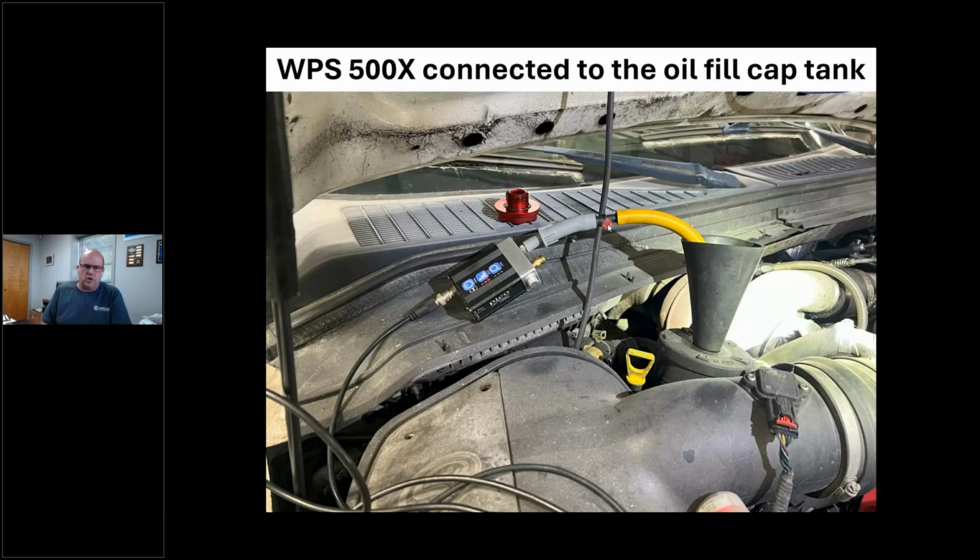If you guys have watched my engine mechanical class with gasoline engines a while back, you'll see me use that. I put that in the intake manifold, all kinds of places. Okay, if you see me do boat stuff, you'll see where I tie that into fuel lines between the fuel tank and the engine to look for fuel restrictions. All right, but anyway, I'm on range 3 here, just to give you an idea where I'm at, and I got the smoke machine funnel jammed into the oil fill cap.